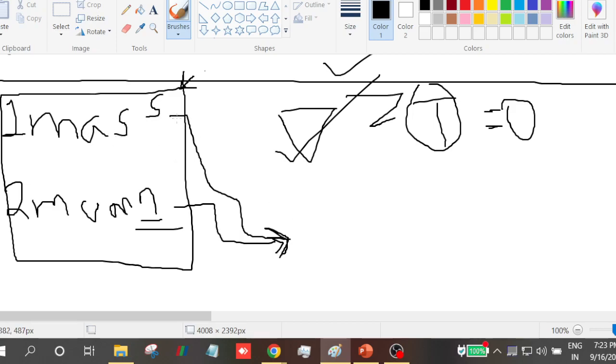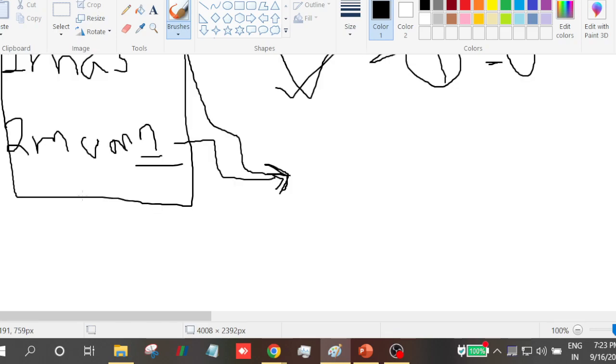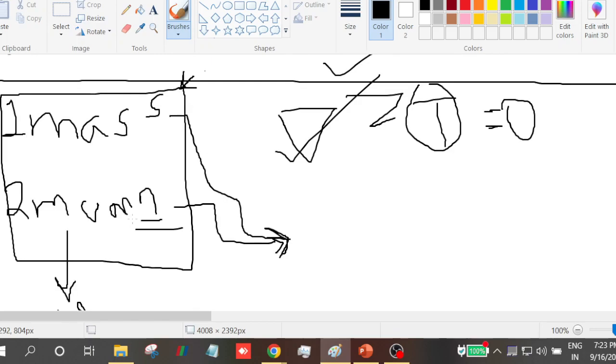See, the mass conservation equation consists of velocities only. Whereas in the momentum conservation equation, you have velocity as well as pressure. But mainly the momentum conservation is applied for velocity calculation. Yes, the equations are coupled, that is, they are connected to each other. That is a good point. That is one challenge we face. The second challenge is that there is no explicit equation for pressure.